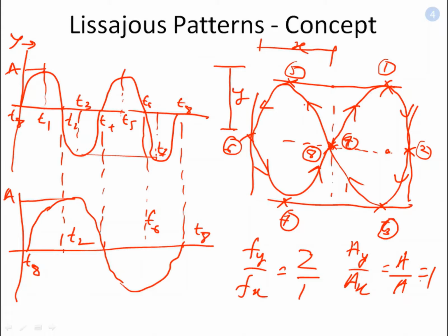A very good example is when you have to find out that two signals are there. Maybe in the case of digital electronics, when you modulate or demodulate a signal, the carrier signal frequency, theoretically, should be at least 2 times the signal to be carried, that is the main signal. So the carrier frequency should be at least 2 times greater than the signal to be measured or analyzed. Then these two voltages or signals can be compared by these two inputs of the CRO, and you can verify.